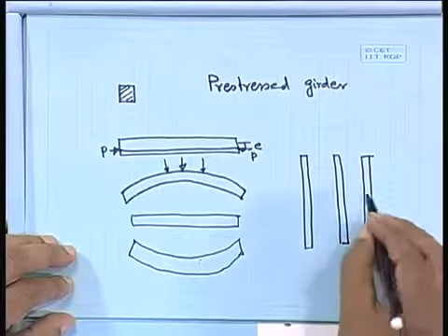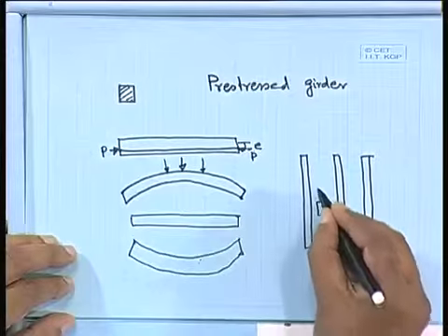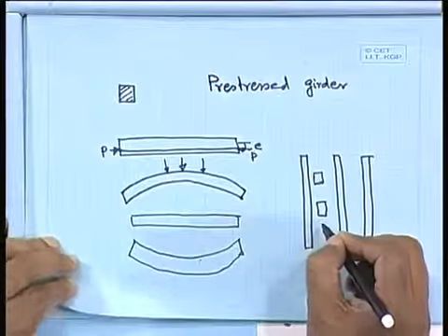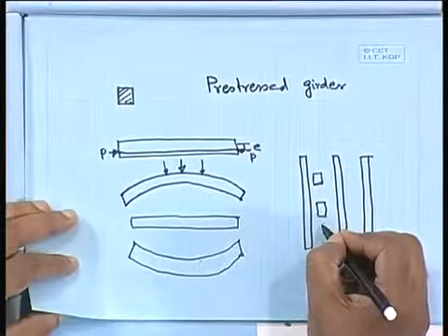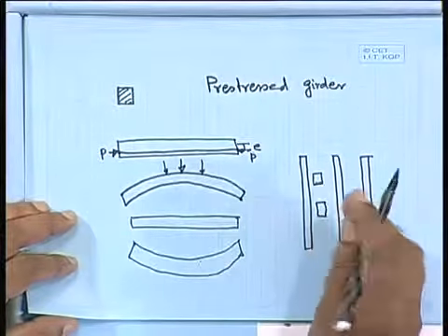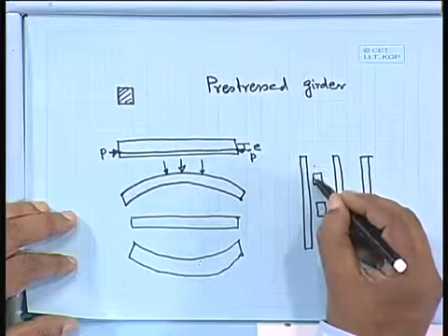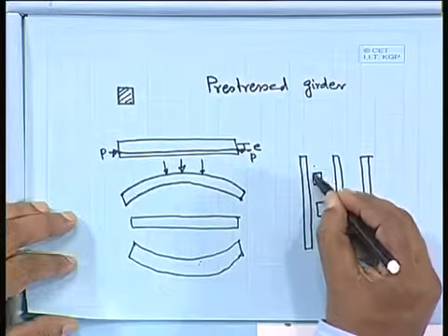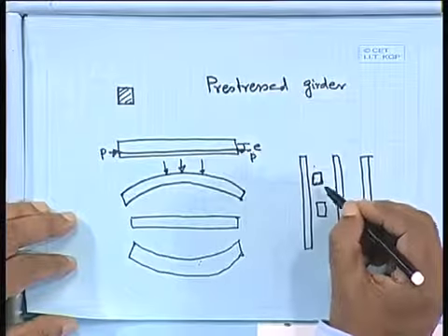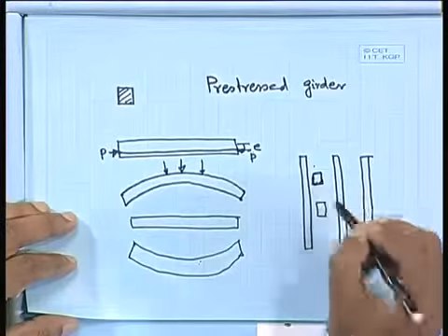Now here we are having that wheel load. This wheel load is coming as a concentrated load. So now if we have the concentrated load here, how shall we take the effective width of the loading? Directly, whatever the impression is, we don't take it, we take a little more. So how much more we can take, that we have to find out.